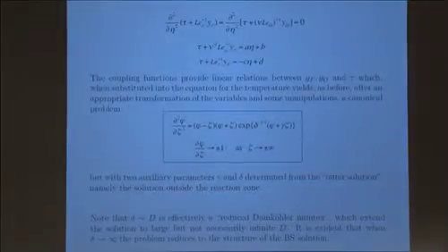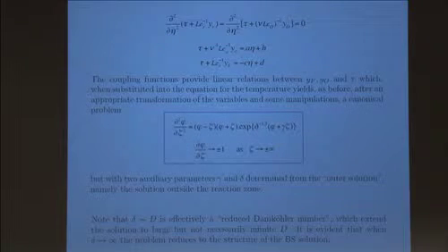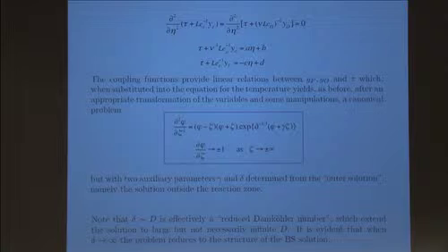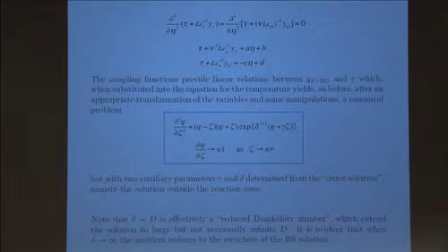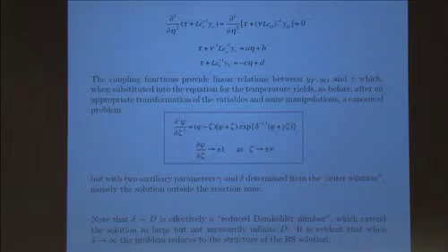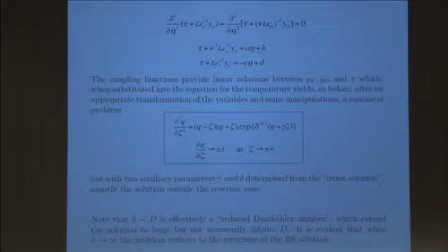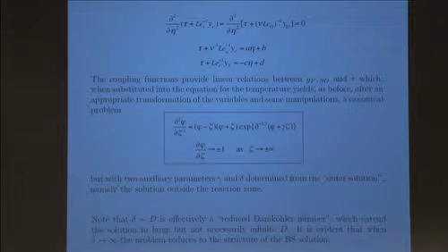Now, gamma, I didn't write it here, but I discussed it earlier. It was exactly the same gamma, and that's why I introduced it then. It's a heat transfer parameter that tells you how much more heat is transferred to one side of the reaction zone than another. And we have seen that it's also related to the initial mixture strengths. So it depends on the boundary conditions, if you like, of the problem.